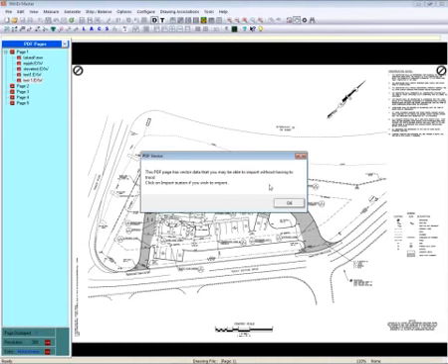Now, this particular drawing does have information in it, vector information, but I'm going to choose not to use it because I want to show you if you have to trace or put items into the drawing when you take off manually. We've got some wonderful tools to be able to do that. But if you were going to use the vector information, this is what you'd see. This PDF page has vector data that you may be able to import without having to trace.